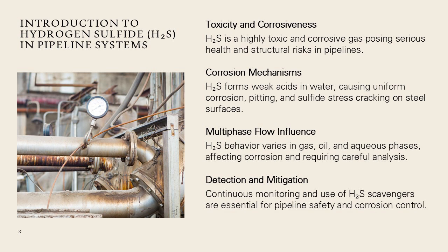Understanding the behavior of H₂S across multiphase flow, gas, oil, and aqueous phases, is a foundational requirement for developing effective mitigation strategies. Engineers must also consider thermodynamic and kinetic factors such as temperature, pressure, water cut, and the presence of sulfate-reducing bacteria, SRB, which can elevate H₂S levels through metabolic processes.